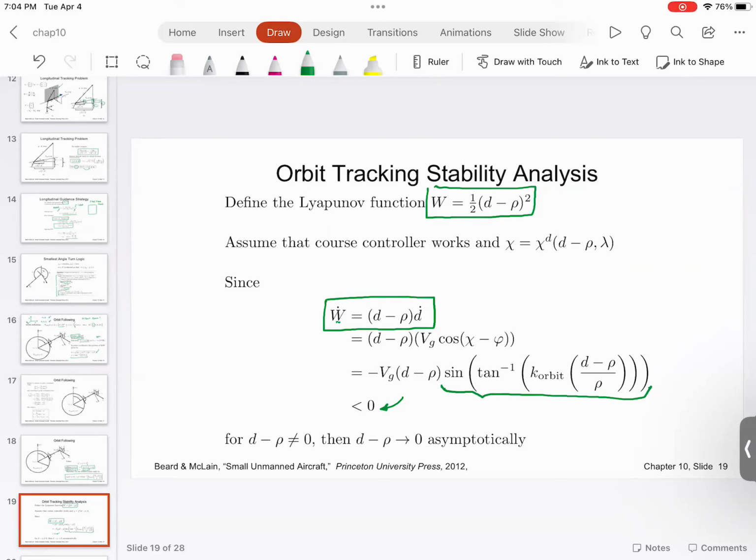If you look at the dynamics that we are looking at, the UAV dynamics, even for path planning, it is a nonlinear system. For nonlinear systems, techniques like PID, linearization, feedback linearization, backstepping, and the plethora of nonlinear control techniques, almost all of these are local in nature. What that means is as soon as the dynamics crosses that particular local region, that controller will not work.